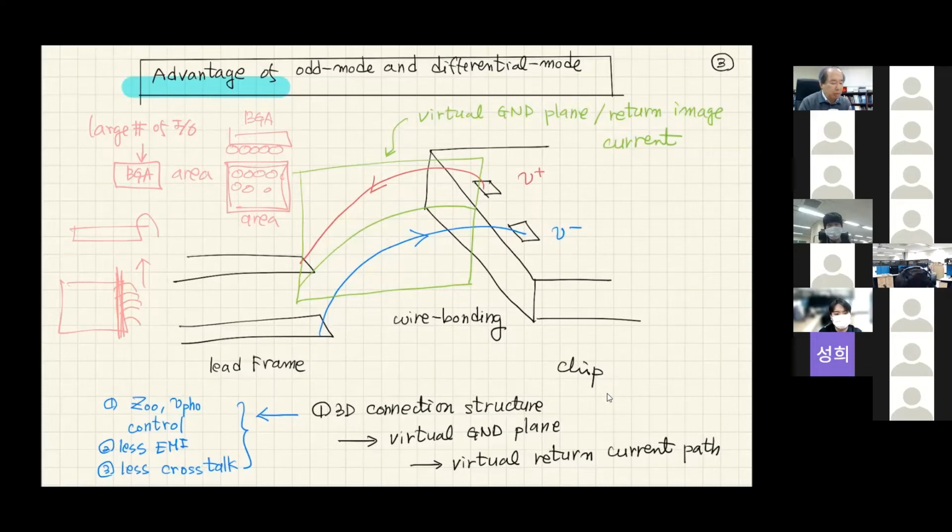Power interconnections usually have inductance, and to minimize the voltage drop and simultaneous switching noise, we have to minimize the inductance. One way to do that is to increase the power interconnections. Also, we want to provide the return current path, always, to be able to send a high-speed digital signal. We have to maintain the ground, so that means we have to have very low impedance ground. In order to reduce the ground impedance, we have to increase the number of interconnections for ground. Because of that, 100 times or a million times more interconnections will be needed in 10 years.